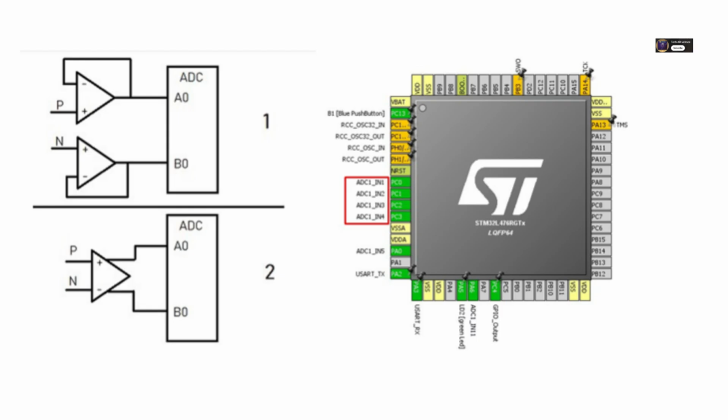Clever. But yeah, typically a single ADC core can only perform one conversion at a time, whether single-ended or differential. You select a channel, convert, select the next, convert, and so on. Unless, that is, you have a more specialized microcontroller with dual or simultaneous ADCs, which can sample multiple channels at the exact same instant.